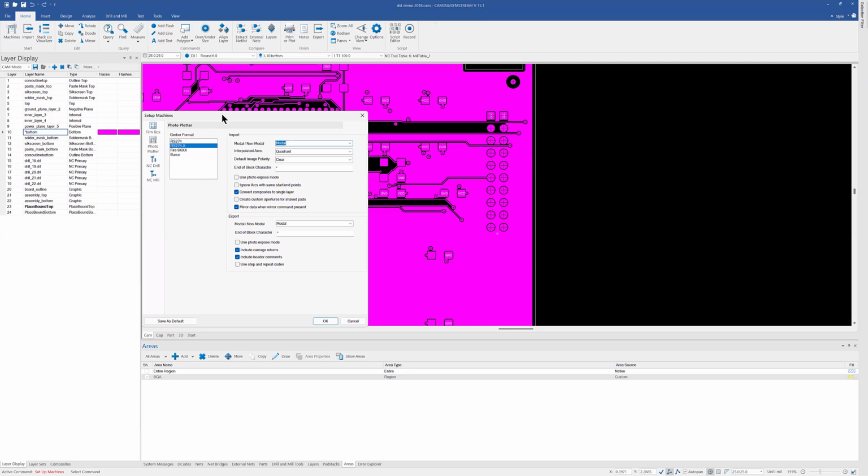So when we import Gerber data, and that Gerber data has a mirror code in it, mirroring means just that, mirror the data, we retain that, but we show it in the main view, top side looking down through the board. So we don't show it mirrored. And that's been the problem, or people have been concerned about over the years.